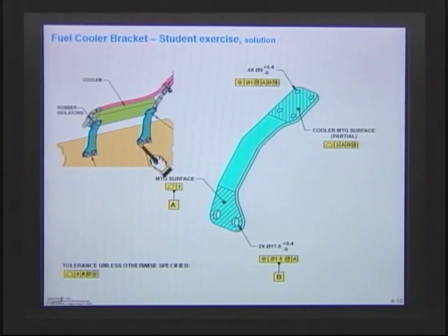It's just going to be pretty hard to hold that tolerance tight enough to be able to get anything up here. Now sometimes I've seen the way the engineer will design it is that I have a hole on one side and a slot on the other side, and I can make the hole the same size as the bolt and then a slot, and that could certainly help. But still we have a serious problem: the distance here is so close and the distance here is so far. So this is probably going to have to be fixtured and able to put it up together.